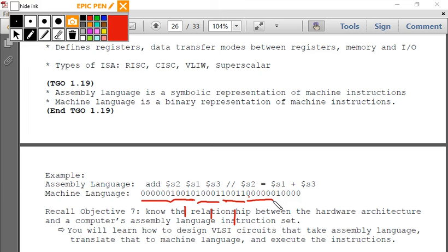Remember, if you shift a binary bit left 1, what does that do to its value? If I have 1, 1, and then I shift it left so it becomes 1, 1, 0, what does that do? It's specifically by what? 2. By a factor of 2, right? So it becomes 3 and then 6. So if I have 7 and shift left, it's 14, right?